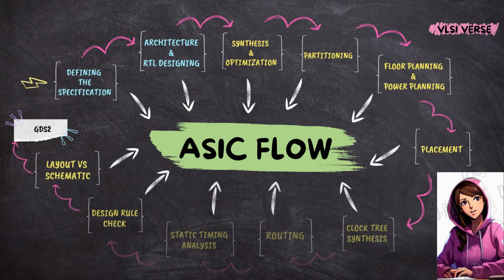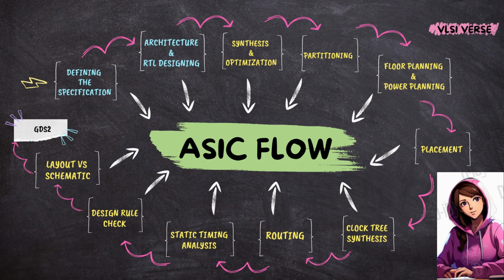Let's dive into the ASIC, application-specific integrated circuit design flow, which is a specialized process within VLSI focused on creating chips tailored for specific applications. The flow begins with defining the specifications, outlining the chip's functionality, performance requirements, and design constraints. Next, we move on to RTL, Register Transfer Level Design, where we describe the chip's behavior using hardware description languages like Verilog or VHDL or UVM.